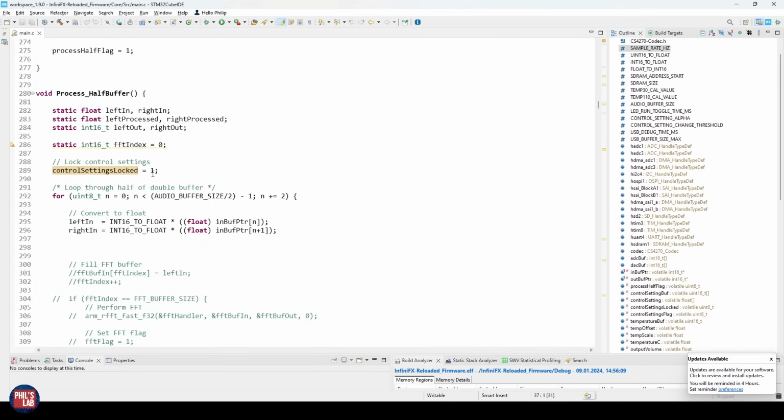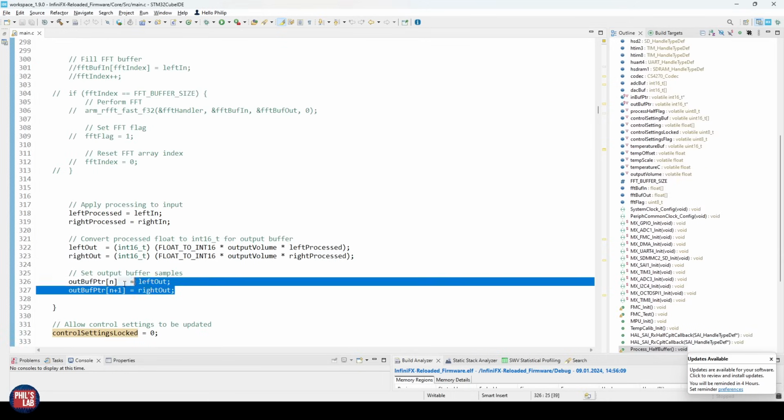I have my processing callback, so I'm doing my I2S, from configuring my I2S feed, so to speak, via DMA, and all I'm doing is looping through the audio buffer that I received from the ADCs, and effectively just sending them out pretty much unchanged to the DACs. There's a tiny bit of conversion between ints and floats going on, because that's pretty much going to happen in any of my audio processing algorithms, and I want to have that as my baseline.